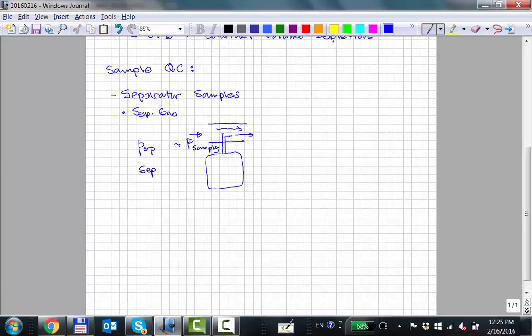So this container, this evacuated vacuum container, is filled with gas. And then there's a valve here that will be closed when they finish filling the container. And they fill this container up to the pressure in the line. So basically the pressure, and probably the temperature, pretty close, are going to be the same as the separator conditions in the container when they close the valve and disconnect it. Okay? That's what it should be.